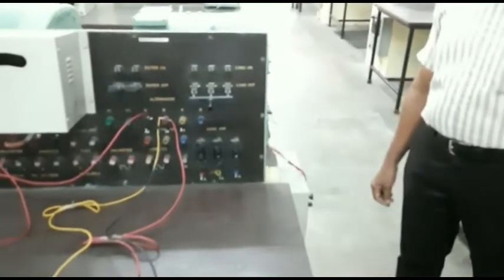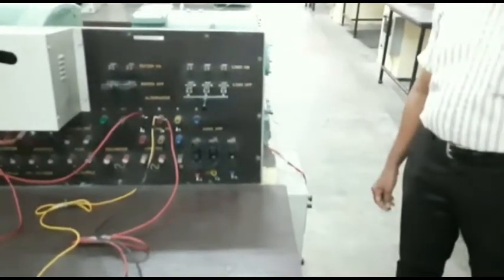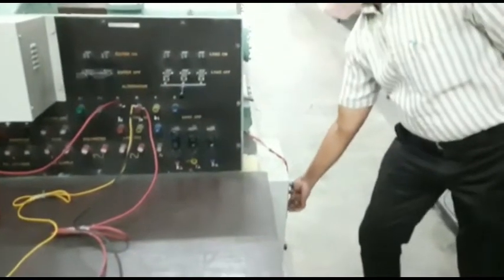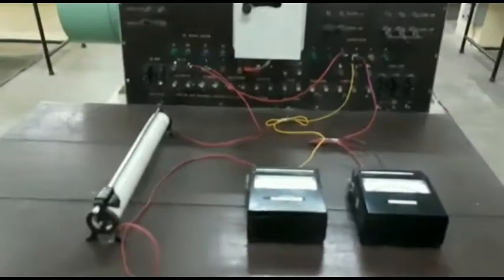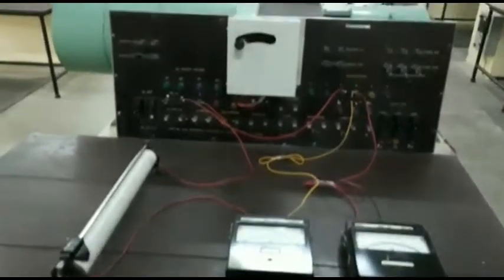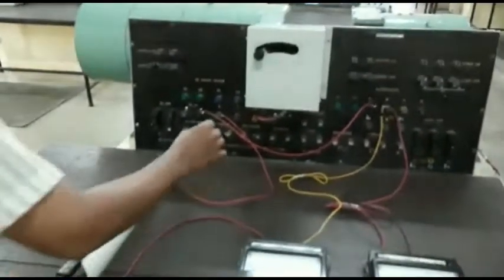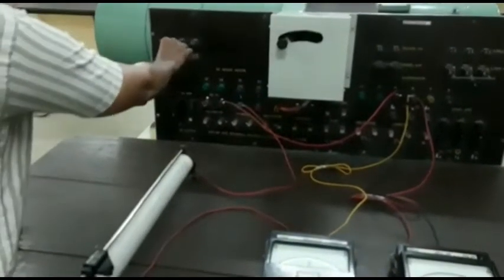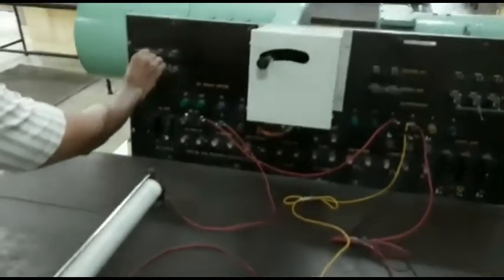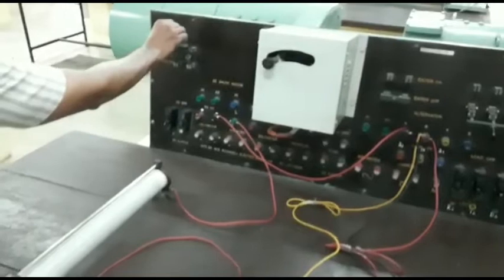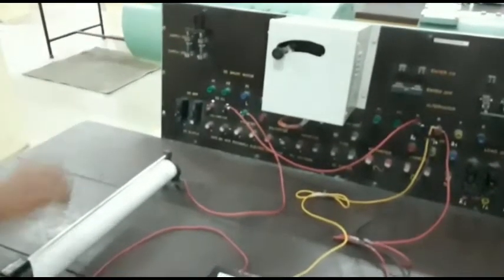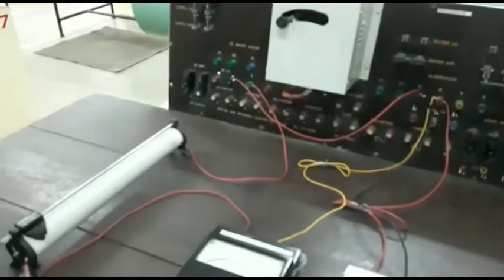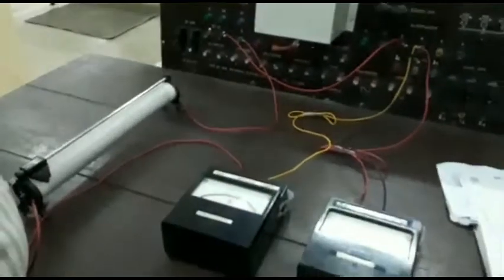So in this, you are giving DC supply. Okay, so sir is going to give the DC supply from the DC bed. Only one reading is enough. You need to measure only the resistance, V divided by I. No need to start the motor. Only thing required is that you have to switch on the knife switch so that the DC supply is available at the point L. And the rheostat is varied and a single reading is taken, V divided by I.